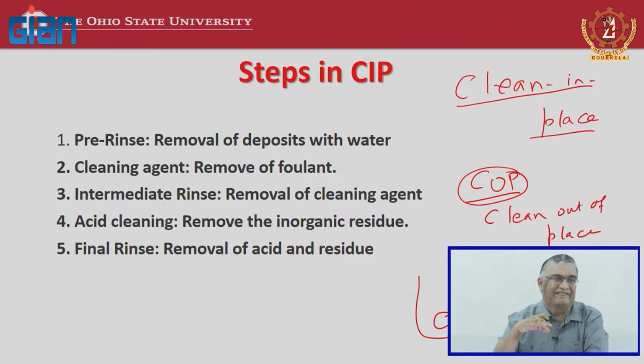The aseptic processing line had a raw material tank, a pump, heat exchangers, a holding tube, a cooling heat exchanger, and then what I call aseptic filling. So, it has multiple components. Disassembling all those things and putting them back is probably going to take a day or two. That means your production is going to be affected, so it is not going to be a very effective process.